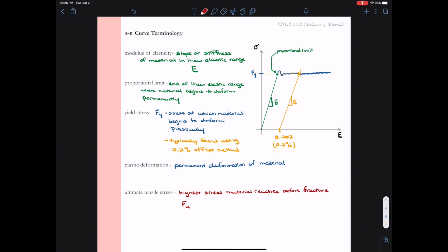And we do that because yielding takes energy. And if you think about an earthquake maybe as it is applying the energy to a building, if we allow the materials in that building to yield, it will dissipate some of the energy from the earthquake, almost like absorbing the energy from the earthquake and then keeping the building in use, because remember, even though it's yielded, it hasn't physically separated. So yielding still means the building is safe. People can escape the building and get to safety.